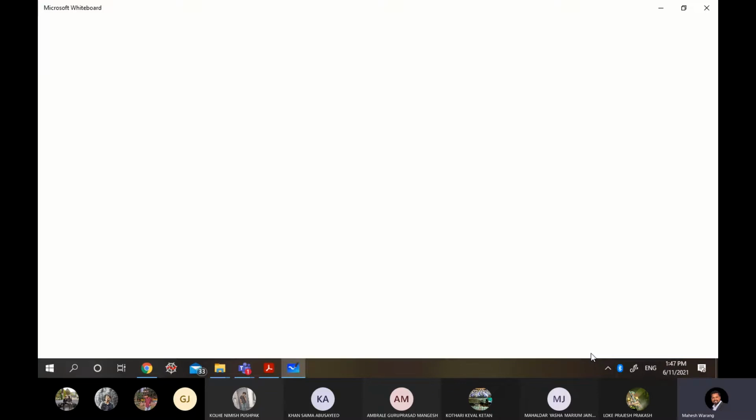So by using that 8282 latch, we have just separated the address lines. You can see at the output now the address lines are separately available, A0 to A19. Total address line separate हो गया. ठीक है. Now the next what? अब data line किधर से लूँ?